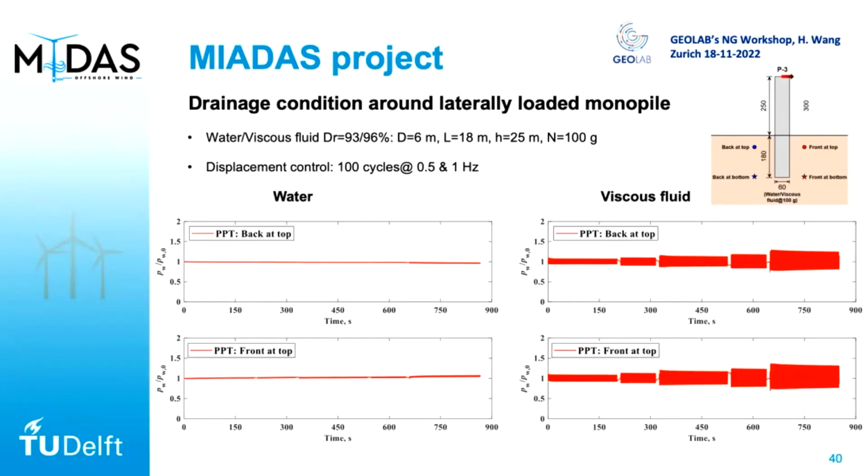But another interesting thing, compared to what we observed in the seismic test, is that in the seismic test you observe a quite large excess pore pressure at the beginning, which then dissipates. But here you really observe a very transient oscillating pore pressure. There is no accumulation. So there is some partially drained response, but it basically means the response is mainly controlled by the drained behavior.